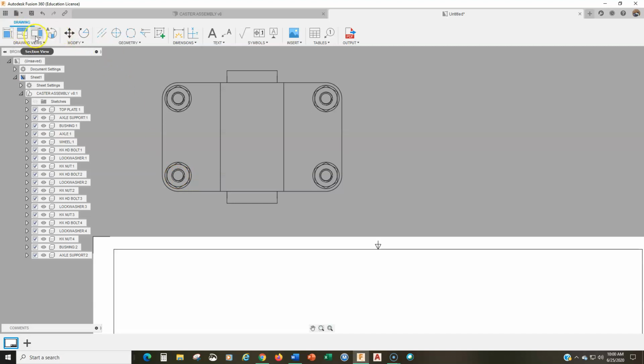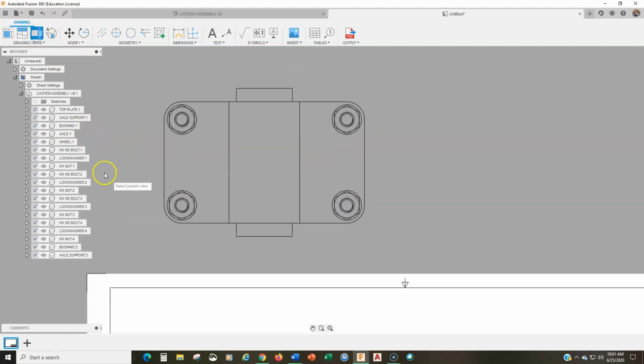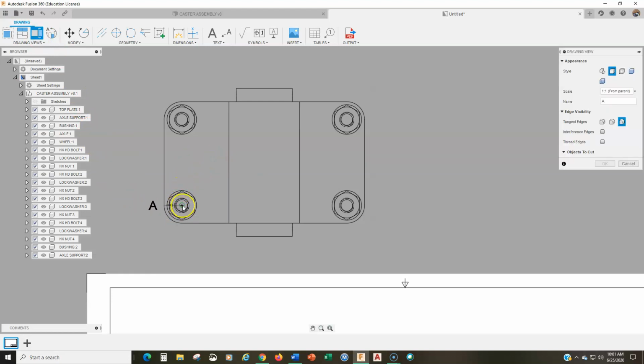Okay, enough talking, let's go ahead and do this. We're going to go to section view, and we're going to pick this as my base view, and I'm going to acquire the center point right there, track out, click, and come straight through. What I'm going to try to do is position this bend in the line, this 90-degree turn, as close to the washer as I can, but not on the washer. I don't want to do that. I want to go right about there, and then I want to go up. Oh gee whiz, how far do I want to go up?